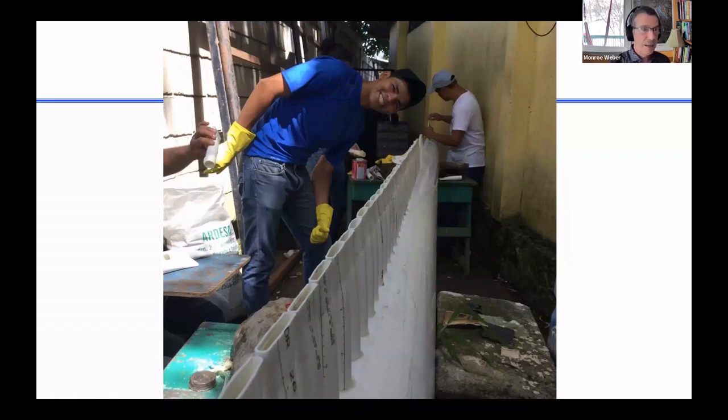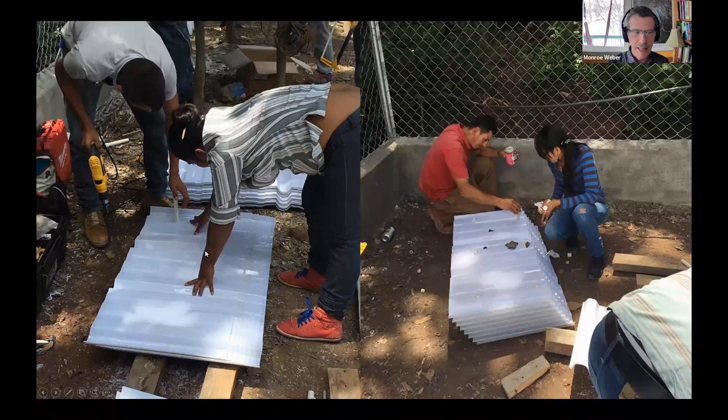This is the fabricated inlet manifold upside down with the diffusers pointed up. Those are the diffusers that will be pointed down and will be delivering flocculated water into the very bottom of the sedimentation tank. And those diffusers are made in a very cool process. I forget if I have any images of that, but they're made by heating up the PVC in hot vegetable oil on a little stove. And it just needs to go to a temperature a little bit above boiling. It's a little bit above 100 C, and then that's enough to soften the PVC so you can mold it.